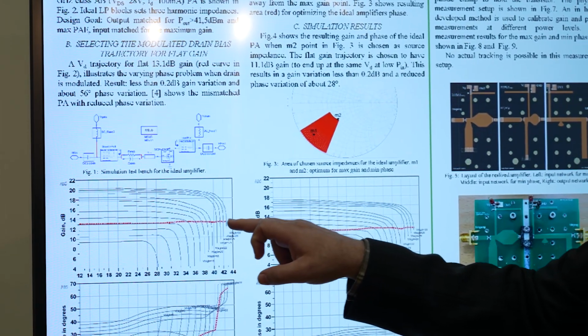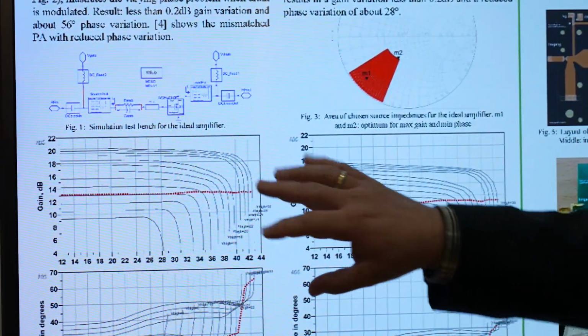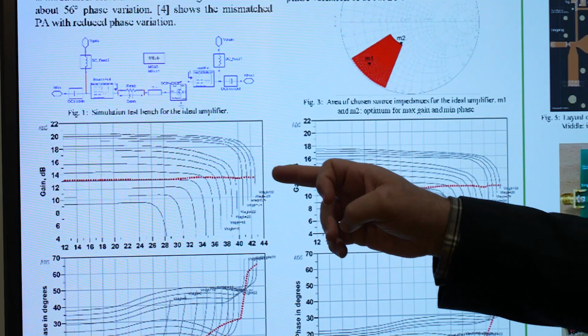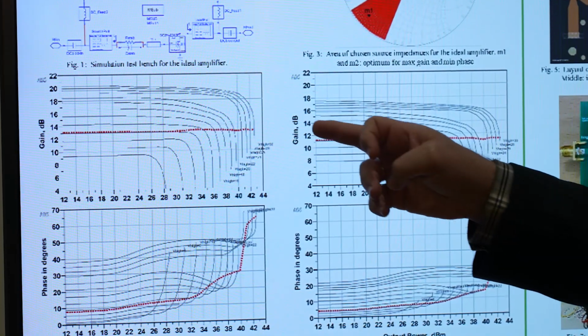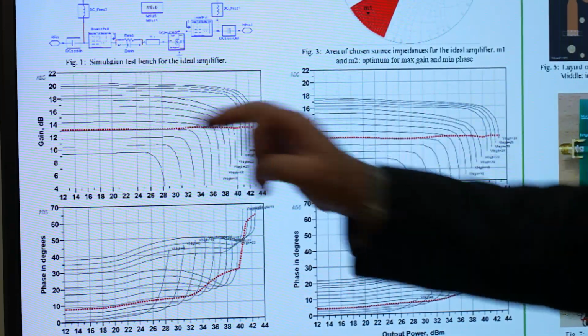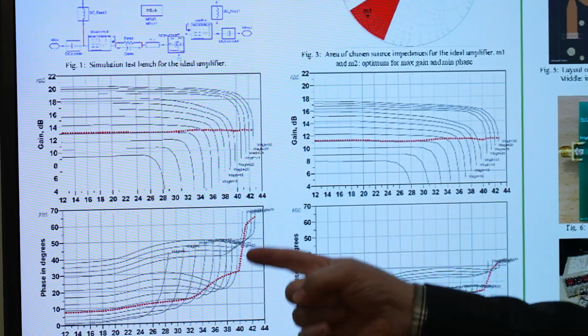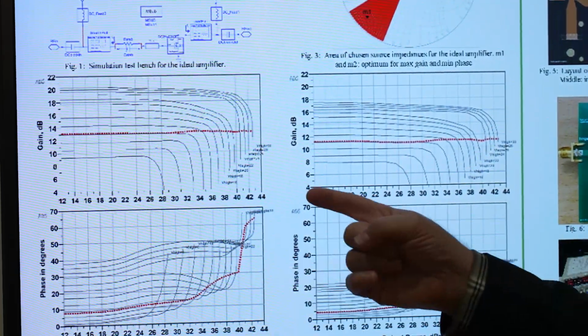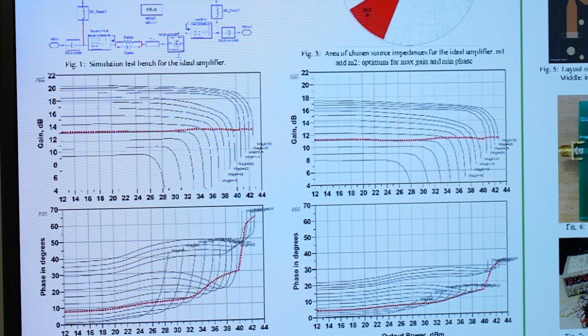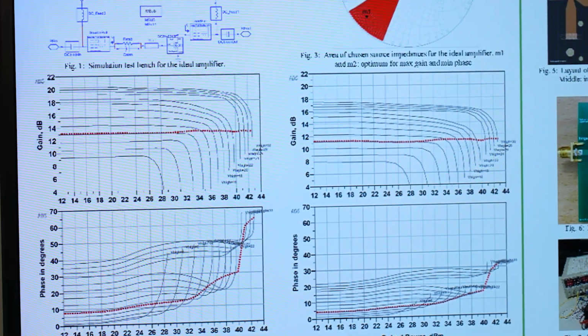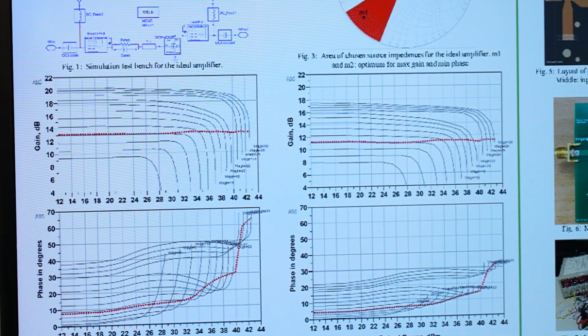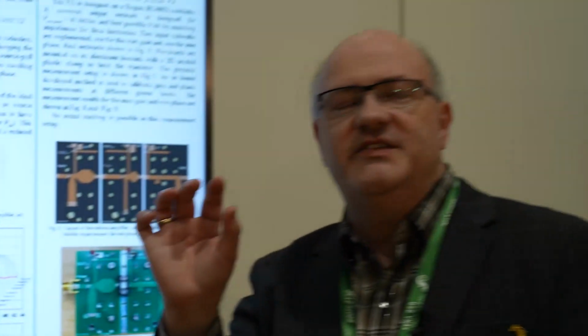And for instance, this is ideal curves with purely ideal simulation, with a flat gain tracking here down to a certain voltage, you still get a huge phase error. Alexander Alt at Cardiff University discovered that if you do not maximize your gain at the input but have a slight mismatch, you can reduce this phase deviation on the maximum PAE amplifier.